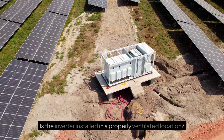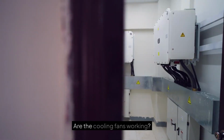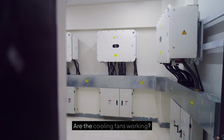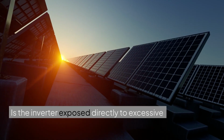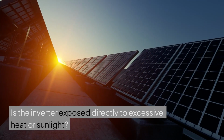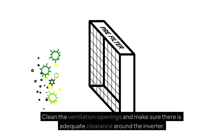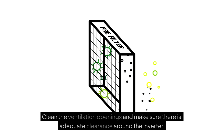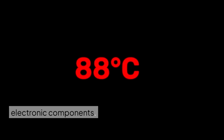Check. Is the inverter installed in a properly ventilated location? Are the cooling fans working? Are the air vents blocked by dust? Is the inverter exposed directly to excessive heat or sunlight? Clean the ventilation openings and make sure there is adequate clearance around the inverter. Never ignore repeated overheating alarms. Continuous operation at excessive temperature can shorten the life of electronic components.